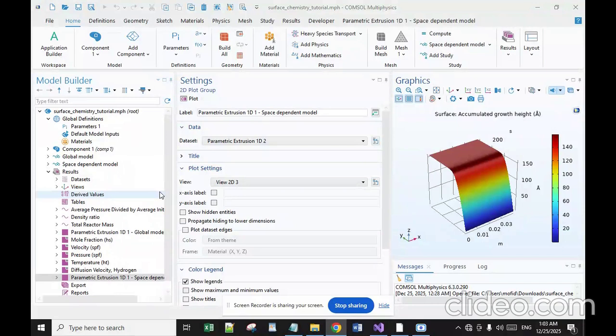These metals can form useful silicides when deposited onto silicon. Mo, Ta, and Ti are deposited by LPCVD from their pentachlorides. Nickel, molybdenum, and tungsten can be deposited at low temperatures from their carbonyl precursors.